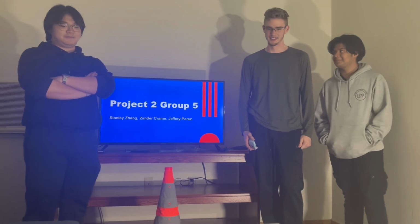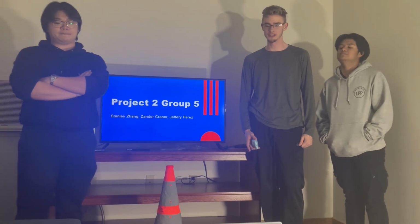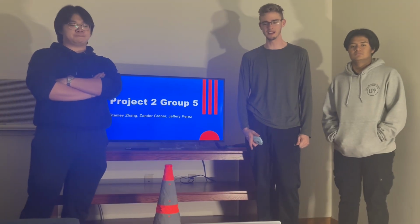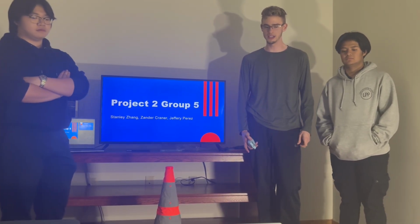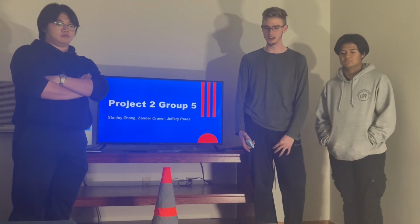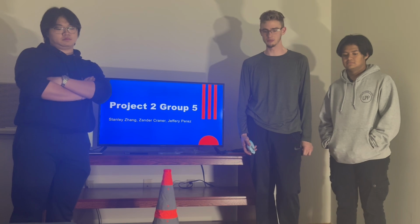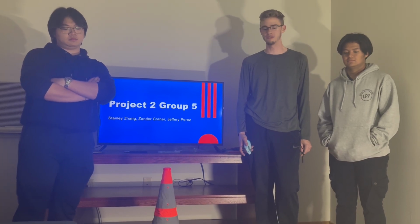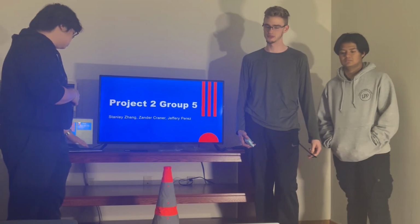And I'm Stanley Zhang. And today we'll be discussing the Lennard-Jones interatomic potential energy for aluminum and iron and how this model can help us understand the mechanical behavior of these two important metals. In this presentation, we'll discuss how we model the interatomic distances for aluminum and iron, how we use those models to estimate their elastic and bulk moduli, and how vacancy formation energy affects their strength and defect behavior.